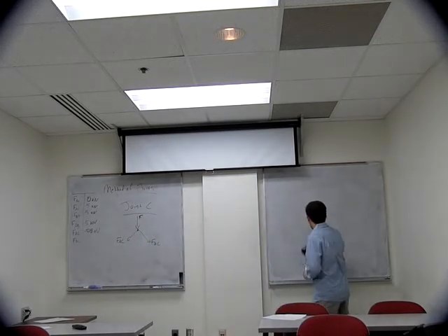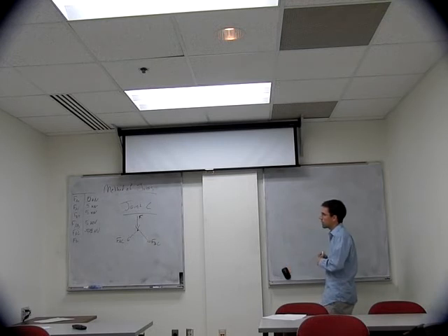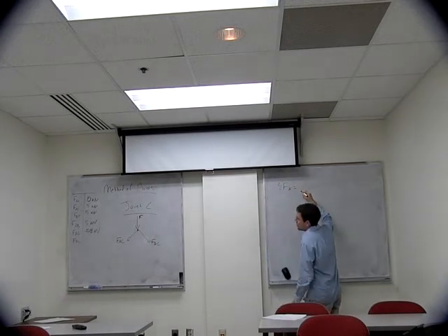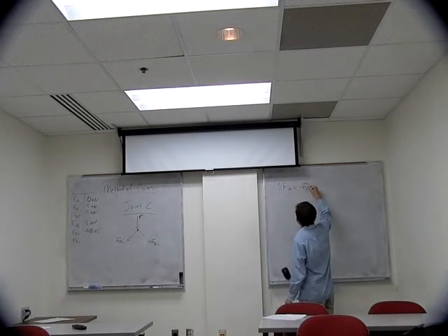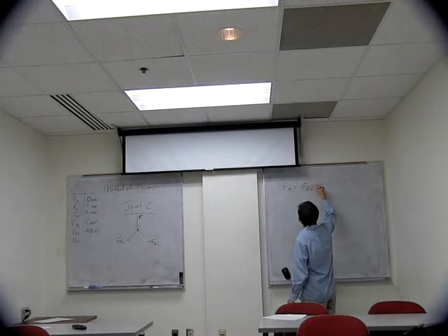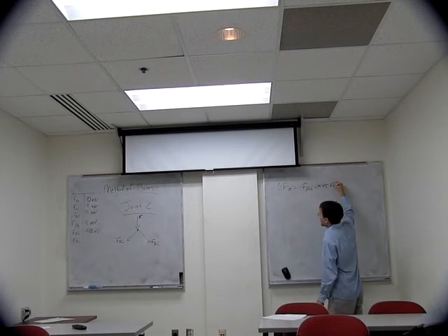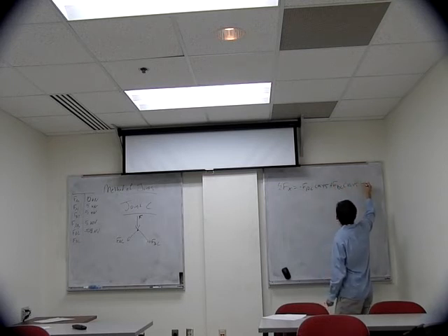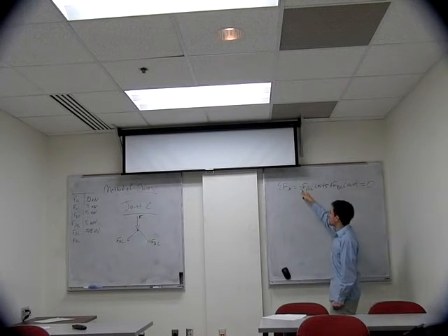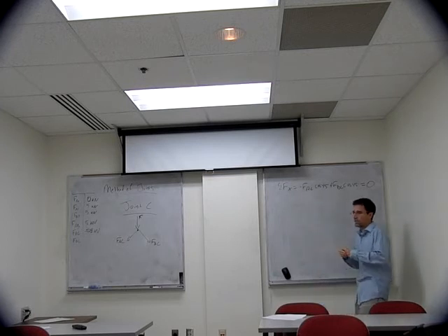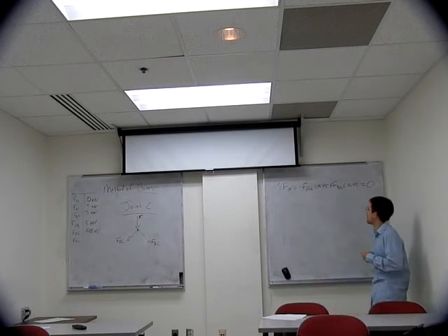Now, again, just like before, we're going to do our summation of forces in x and y. We'll start with x. We have negative FAC times the cosine of 45 plus FBC times cosine of 45, which we know has to be 0. Again, this negative comes from the fact that the x component of the member force in AC will be to the left.